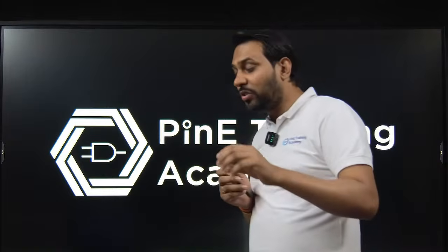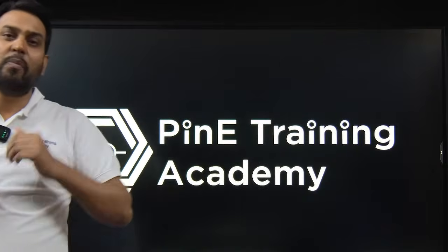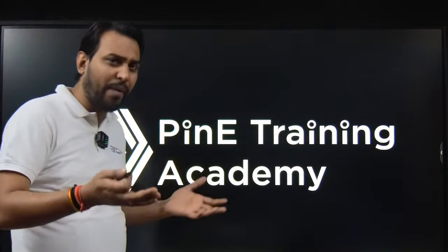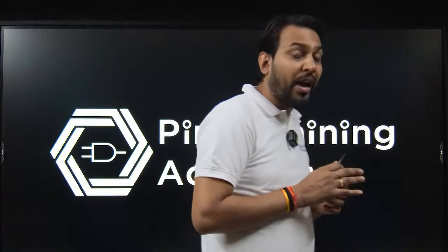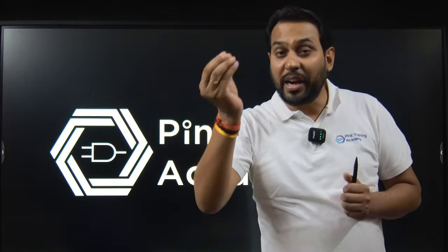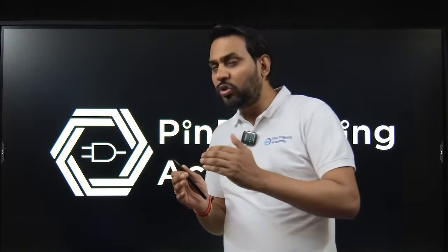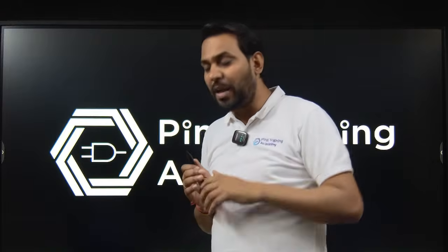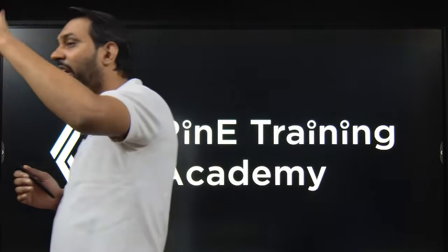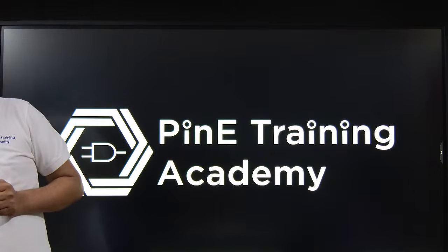Whenever you talk about a MOS amplifier, whether a common source amplifier, common drain amplifier, common gate amplifier, differential amplifier or op-amp, anywhere you talk about an amplifier, you convert your signal into a small signal model, and there you find the dependent source. What is the meaning of a dependent source? A dependent source means a voltage or current that depends on some other circuit element. You can define this voltage or current with respect to a dependent source.